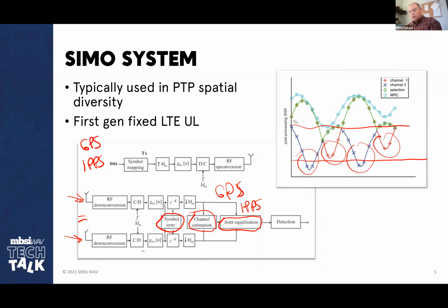Now, one of the things that you notice about this fading that goes on in the channel is that it is frequency and time dependent. So if I were to look at this in 3 dimensions, if this graph would have thickness, then I would see fades within the channel on certain frequencies, on certain OFDM carriers, if this were an OFDM system, and others would not be faded. And the sum of all of this ends up making the channel response look similar to this graph. So the job of the equalizer here is very important.